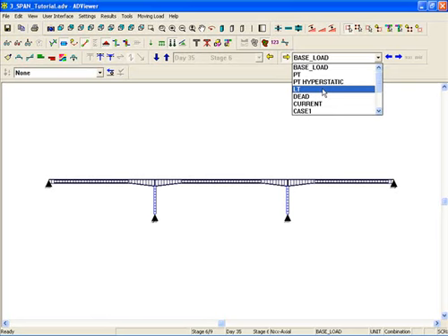LT represents the long term. Dead represents dead load minus the post-tensioning and also long-term effects. Current includes the base load plus the PT and long term. It would also represent the last day in the sequencing in the pre-construction phase.